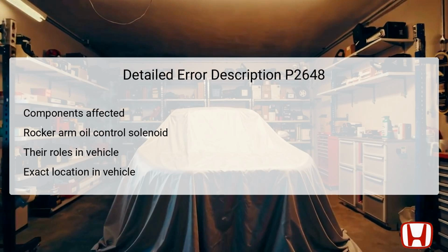The PCM monitors the performance of this solenoid by sending and receiving signals that indicate its operational status. If the PCM detects that the signal return is incorrect, it flags this issue as a potential malfunction, enabling the technician to troubleshoot further and ensure optimal engine operation.